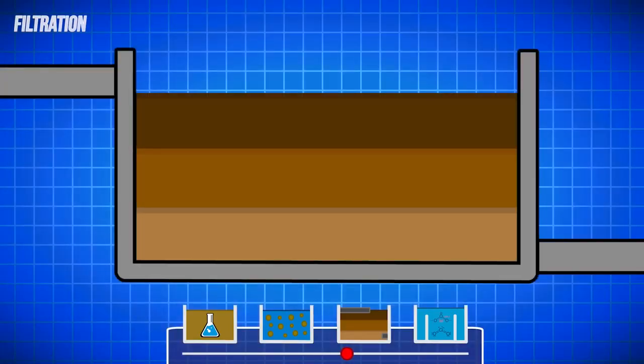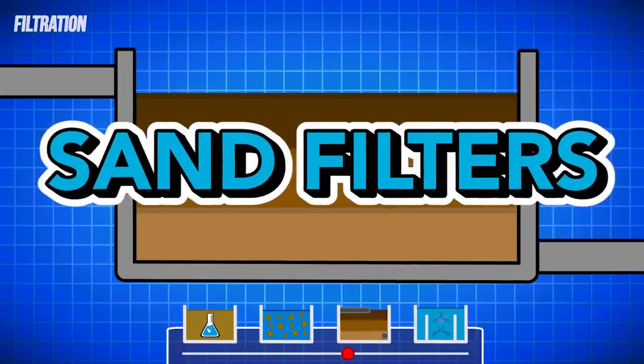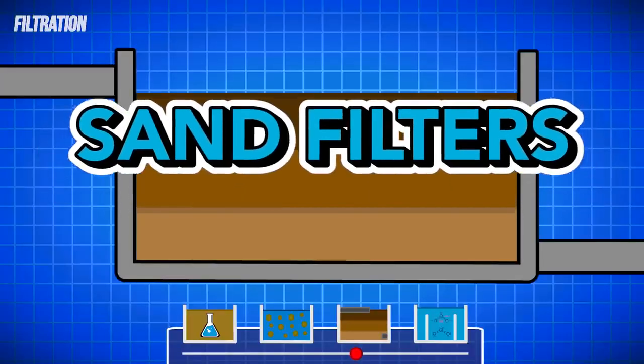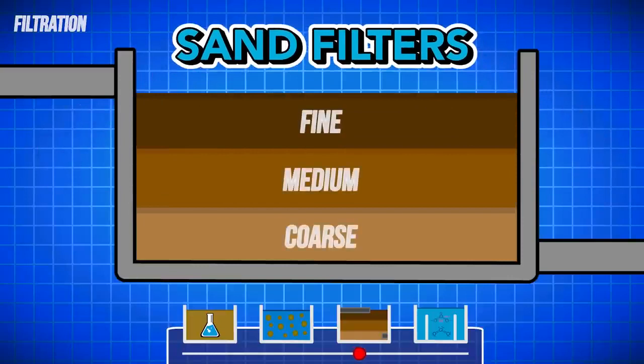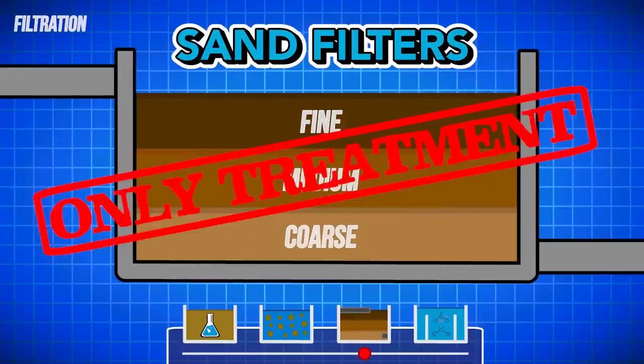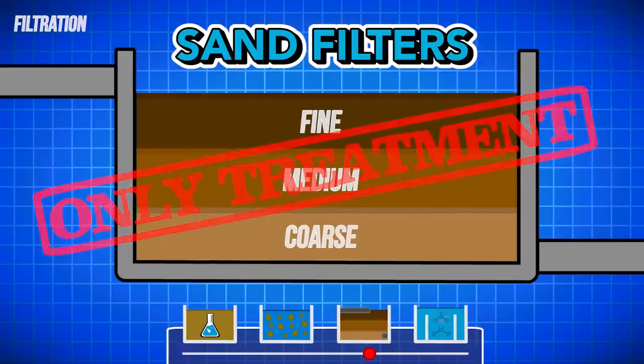Nearly every potable water treatment plant will use a sand filter for this process. Even in plants where engineers may not think it's needed, often sand filters will be added simply for extra measures to ensure clean water at the end. Sand filters are exactly what they sound like, a basin of fine to coarse sand that filters water. It would theoretically be possible to treat drinking water with only sand filters, but that would result in frequently clogged sand filters, resulting in lower efficiency and more cleaning time.